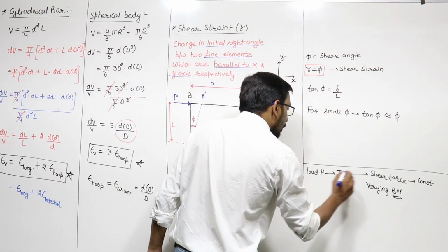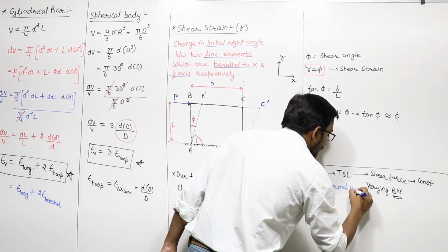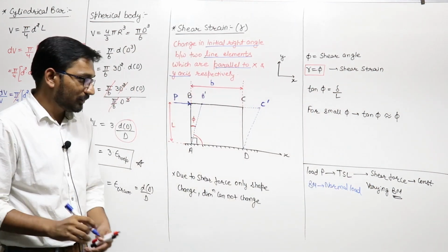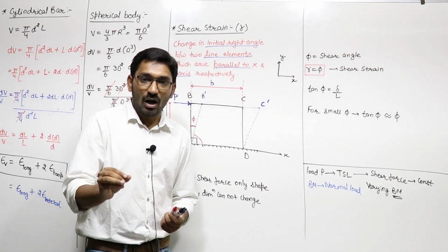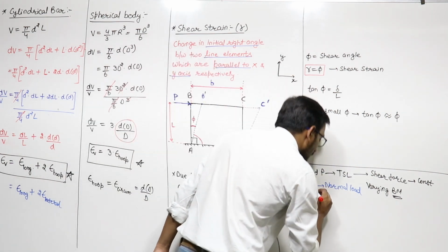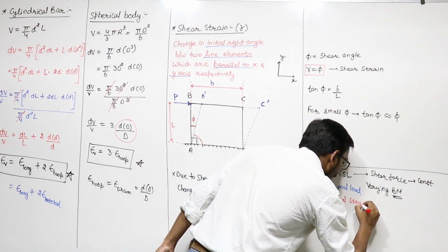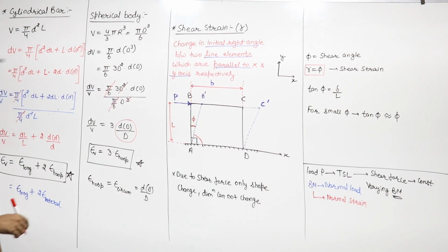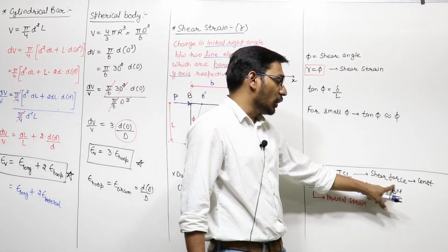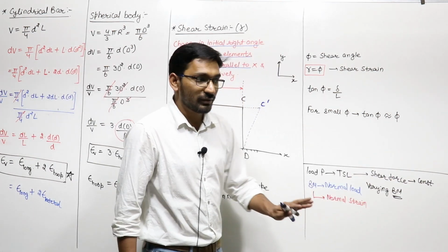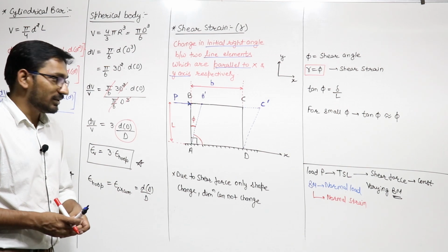So one thing I can say, you know already, this bending moment is a normal load. Just remember one thing, it is a normal load. Because of normal load, what happens? Normal stress. Because of normal load, which strain is there? Normal strain. Because of bending moment, normal strain must be there because it is a normal load. And because of this shear force, shear strain will be there, right?